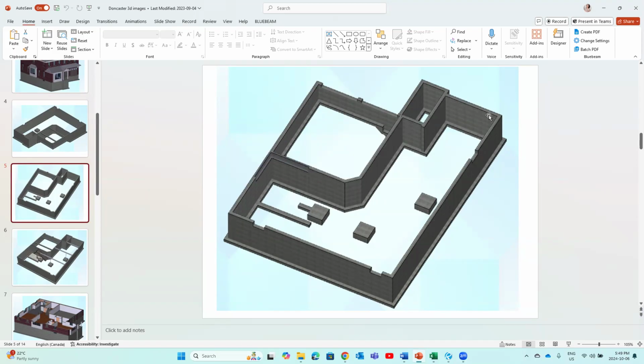If you pay attention to the drawing, you see the depth of the foundation wall for the basement is different from the depth of the foundation wall to the cold cellar and the depth of the foundation wall to the garage. We easily found that out, right? That's why we separate them. Because when we calculate the formwork for foundation wall, we are going to use the length again.